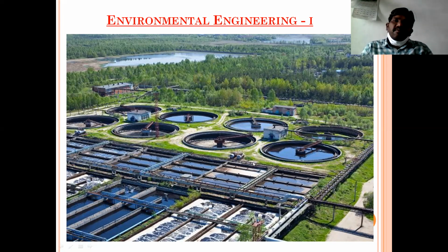After that, we should go for proper alignment with respect to the already existing underground pipelines, telephone lines, and any other existing lines. After that, we have seen the third point, the bottoming of trenches. If the trenches have any zigzag and ups and downs at the bottom, we may go for a concrete bed, and we have seen all the consequences.